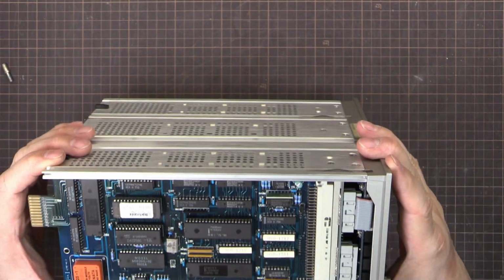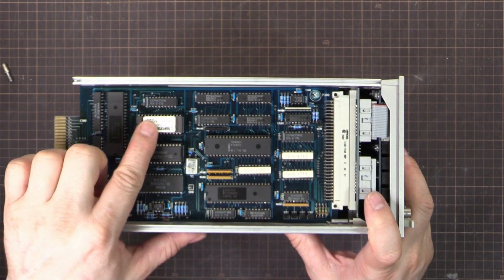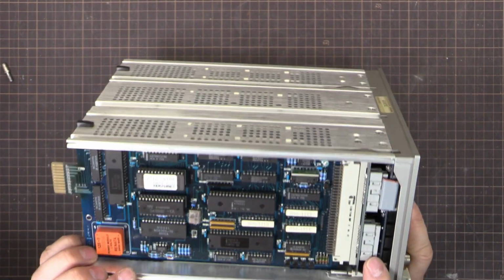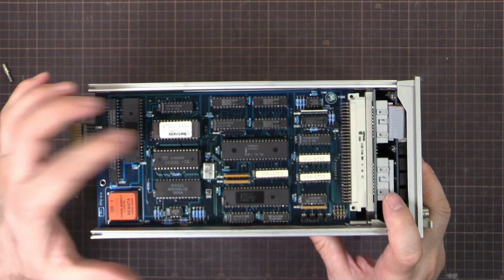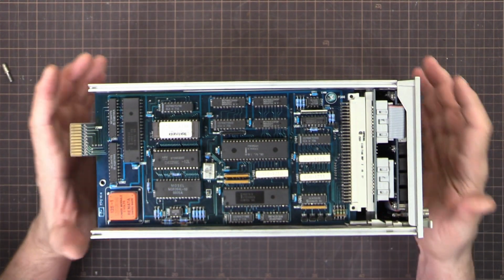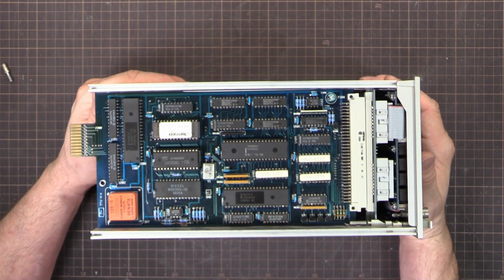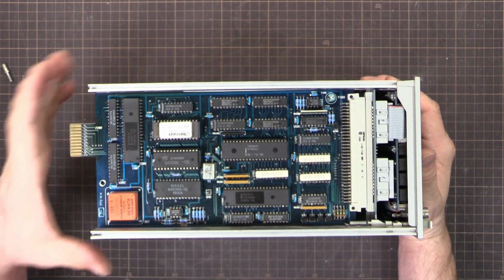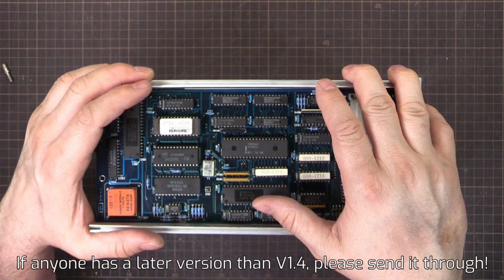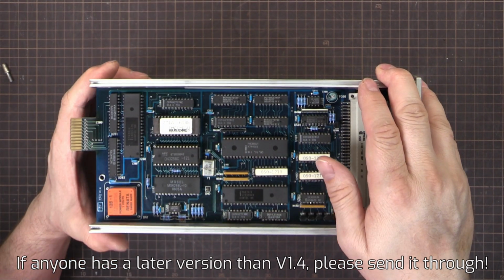Let's see what's inside. So we've got the CPU board here. We've got our firmware here. This is just a standard EEPROM. What's that? Yeah, 27256. Standard EEPROM chip there, UV erasable. That's version 1.2. Now, I had a bit of a poke around online. I found version 1.3, and a nice member on the TekScopes groups.io page has sent me version 1.4, so we will upgrade that to version 1.4. I'm not sure what the changelog is, what's the difference, but it's definitely not going to hurt to upgrade that. I've got the gear to do that, so we'll run through how to do that.